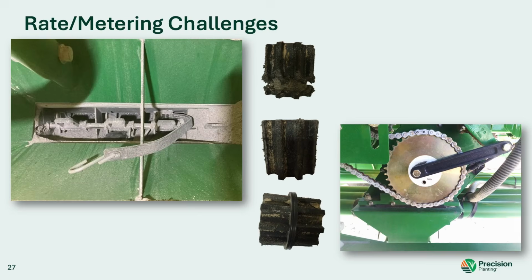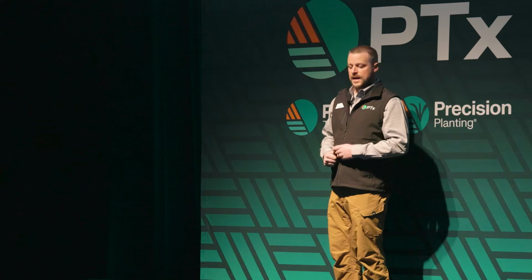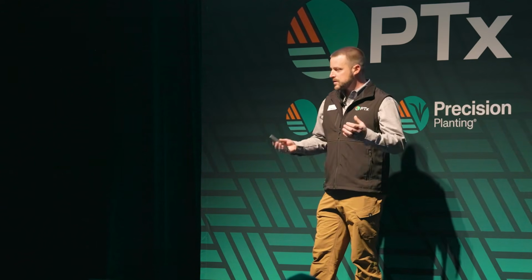What if I get a little bit deeper into some of those challenges? As I'm filling the drill, I'm up on the top, I drop a tarp strap in. Before I can get everything shut down and let Dad know, that tarp strap is covered up with fertilizer. Okay, so if I don't find it, or maybe I'm too afraid to tell Dad that tarp strap fell in, maybe the part of the fertilizer plant that made it into the tank actually chewed up my meter, and now the displacement of that meter is different than it was before. Or some of the corrosion that I've got on my meter has harmed my agitator, it's not working, pieces are broken, and I've got susceptibility for some partial flow on some runs.